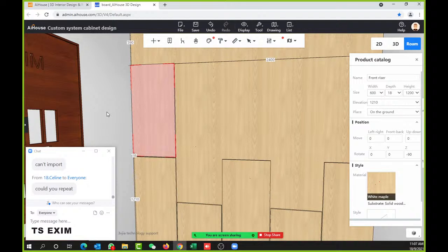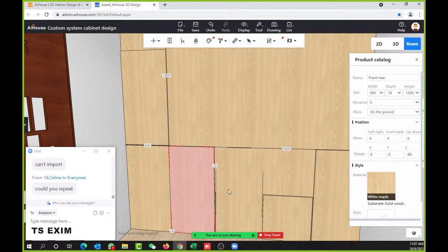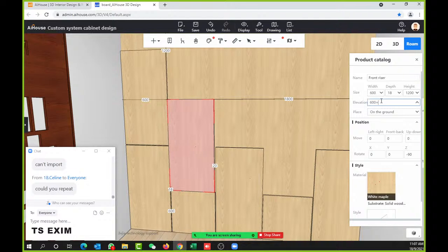Okay guys, time's up. Okay, so here we copy one more banner, Ctrl V also, and this one the banner we know, right, 600. So with elevation here, put 600. Then maybe I'll add another 10 mm gap. Then we have a gap. And here remember we need to add another 10 mm gap also, followed by here 610. So we add 10 mm gap.